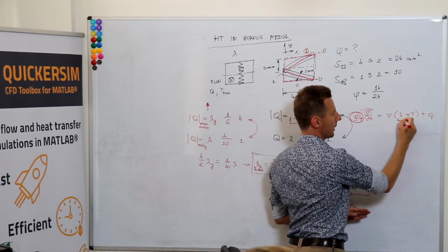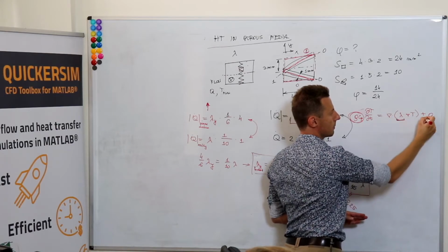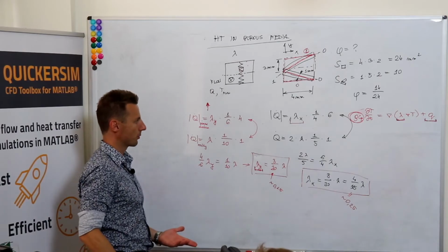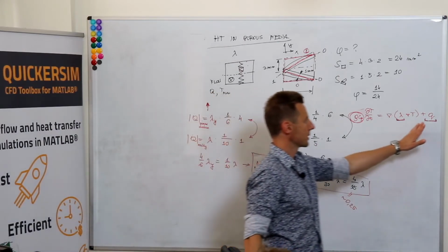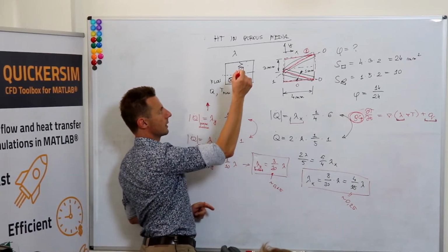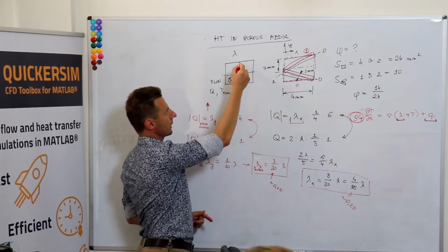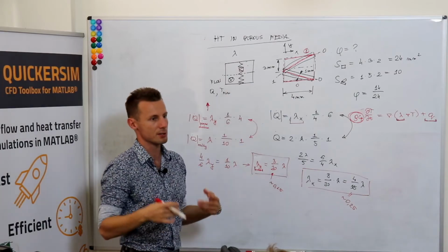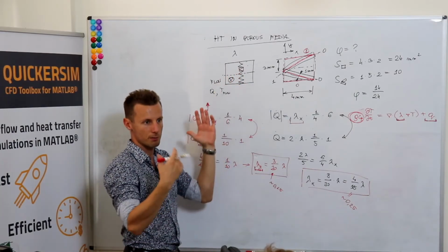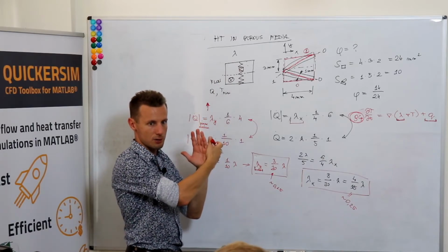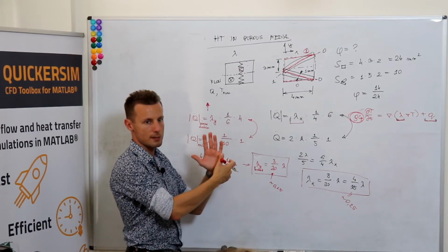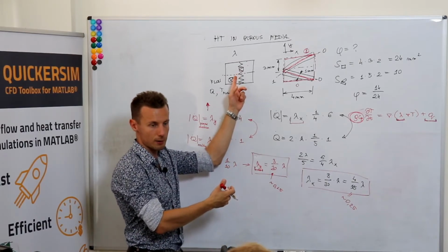We have already gone through that, but we still need to derive the proper formula for the source term. Because if you've got the flow that is moving in this direction, you've got heat conduction in the solid part of the porous medium, then you need to couple the fluid flow across the heat exchanger with the temperature distribution that you will be solving for in the solid structure.